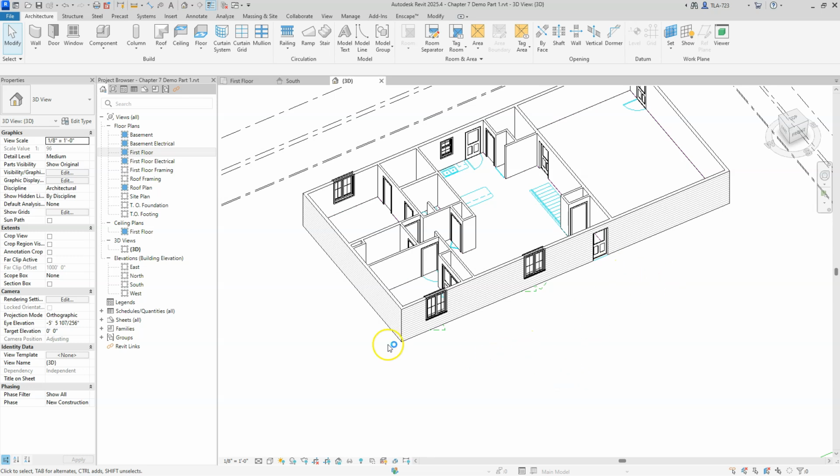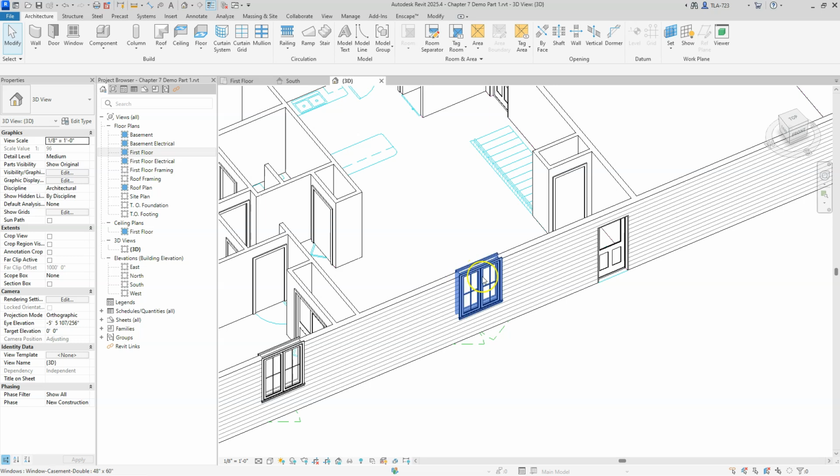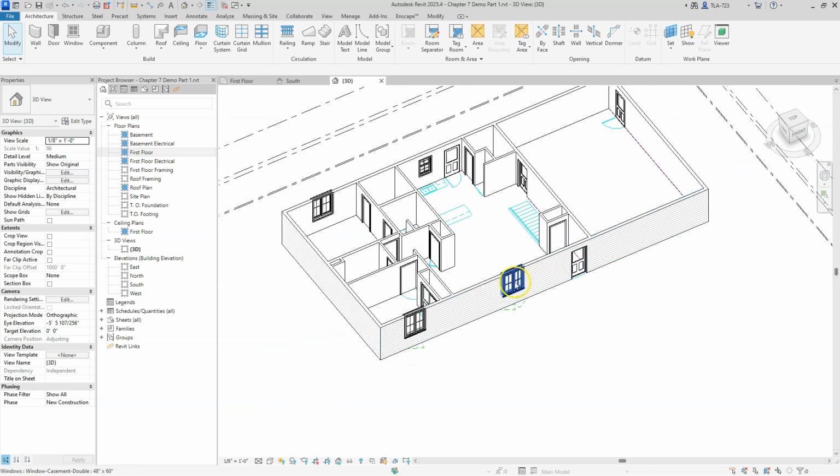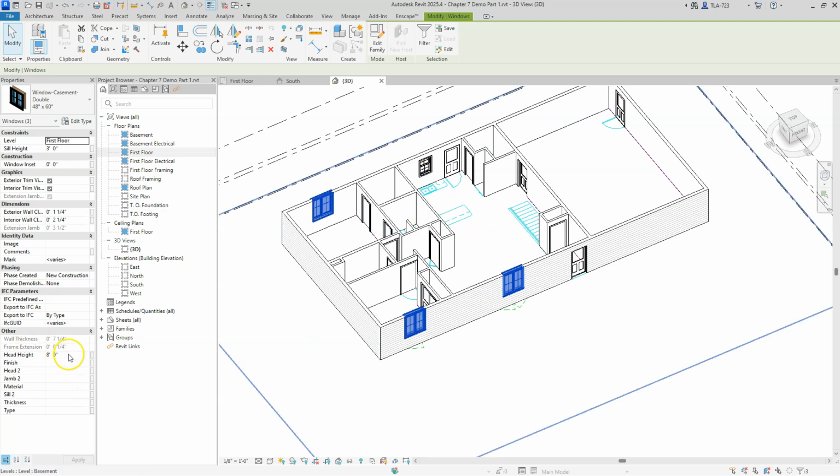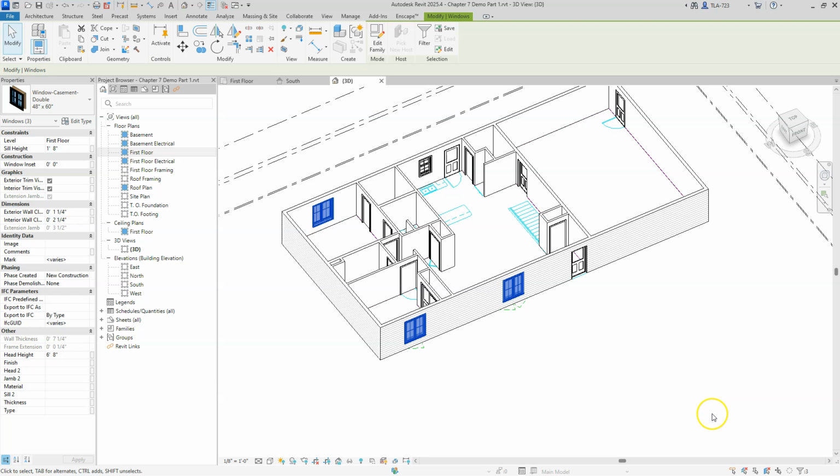It does look like the height of this wall is kind of running into these windows a little bit. So possibly these windows just came in a little bit high. That's one thing that we can pretty easily fix. So let's go ahead and select all 3 of these windows. And we're just going to set their head height to 6'8". 6 space 8. Enter. That'll bring them down to a height that's more appropriate for residential.